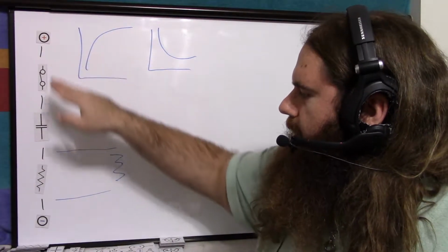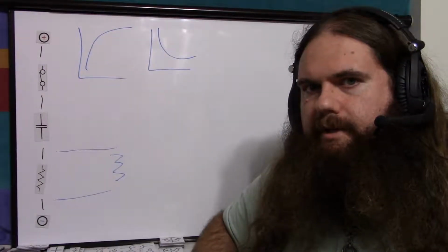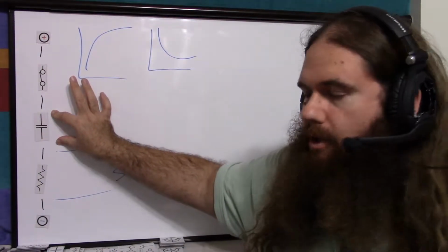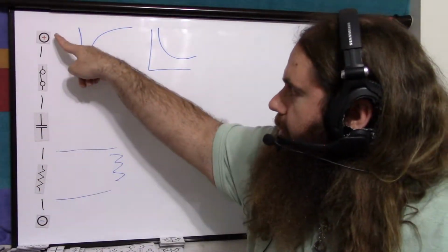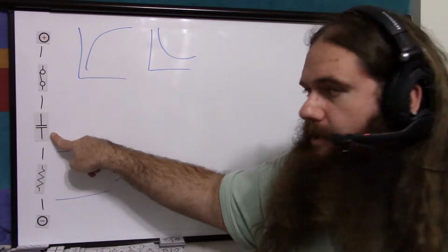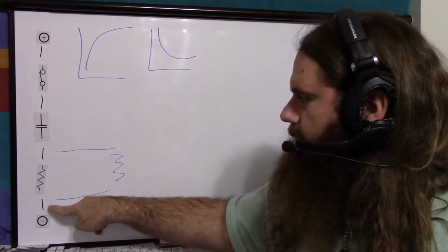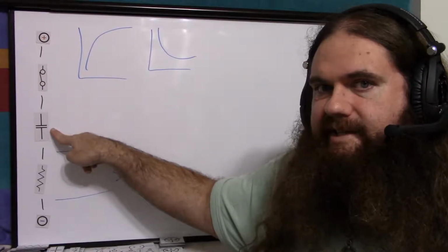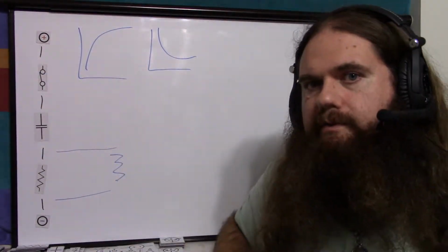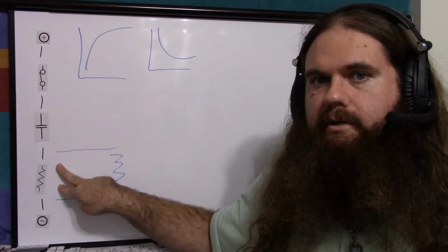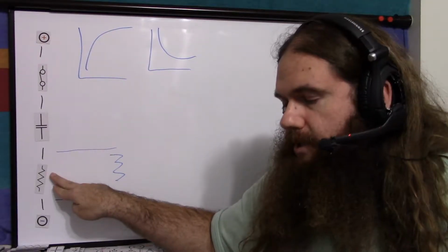So now you've got 5 volts here and 0 volts here. But the capacitor is taking everything, right? The capacitor is charging, which means there is a current. There's no current through the capacitor, but there's a current from here to here. And then on the other side, let's say we do it from here instead. So the negative electrons are being pushed through the resistor into this end, which is pushing electrons away from this end, back here and through to the negative. So there is a very large current through this resistor. V equals IR, Ohm's law. Large current means large voltage.